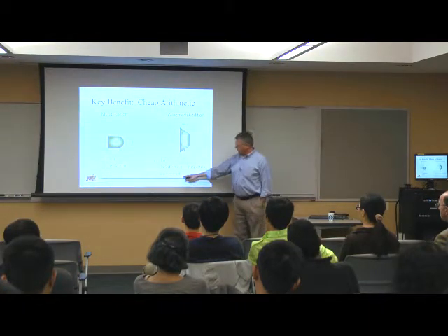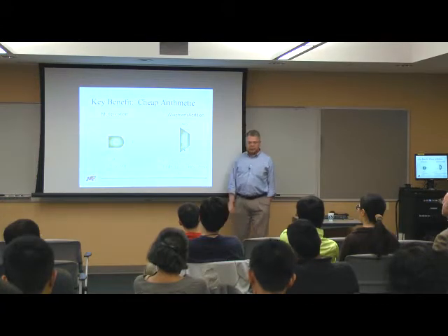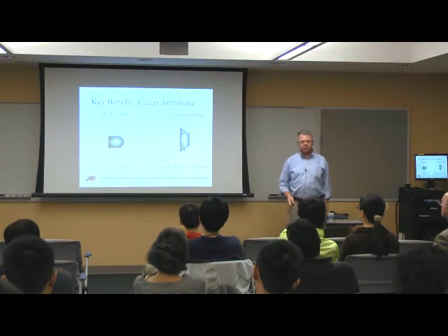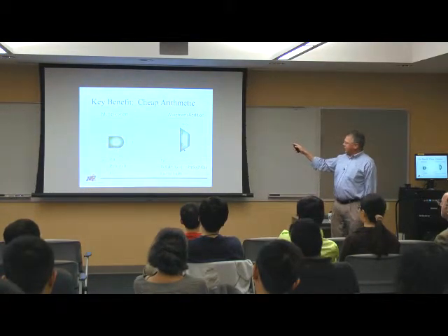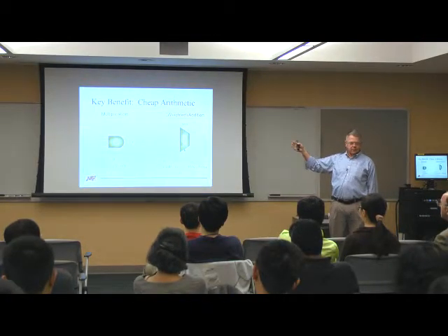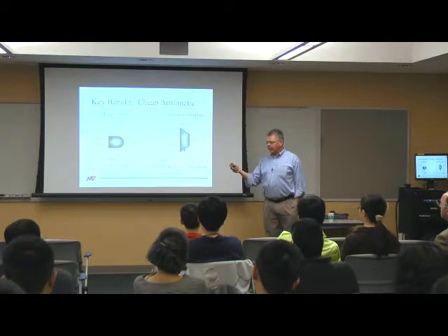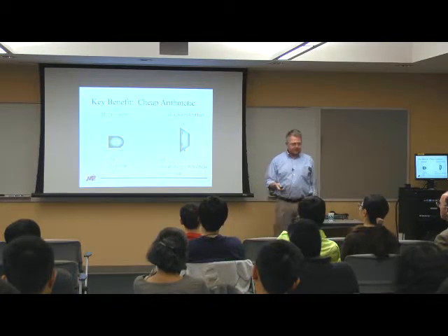So I've just done a scaled addition, where I have the select value times the probability of the input on A plus 1 minus the select value times the probability of being a 1 on the input of B. All right, so I've got multiplication and addition, very cheap. What's a multiplier? One AND gate. What's a multiplexer? Well, it's 2 AND gates and an OR gate. So it's very cheap to do arithmetic here. This is the good thing.